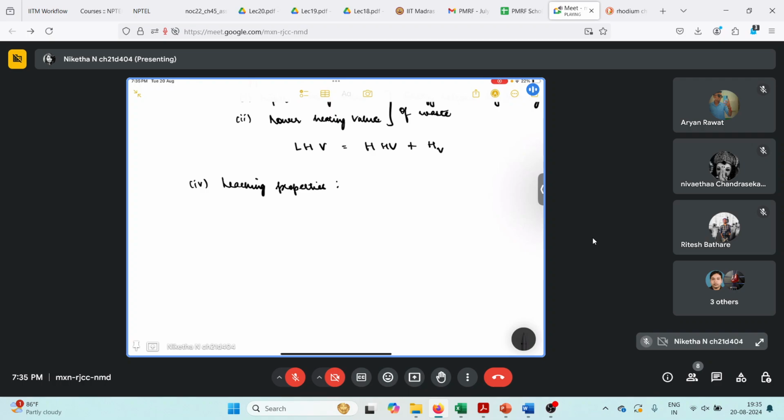So when we put this solid waste in a landfill, we have to determine the leaching property of that waste, what kind of toxins are emitted by the leaching test. All this has to be determined, and only then will we know if the waste is safe enough to be disposed of in the landfill or not.